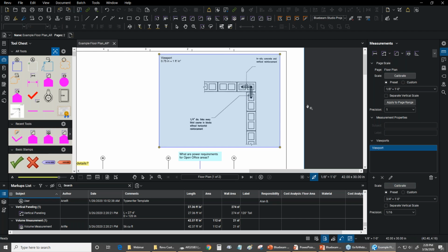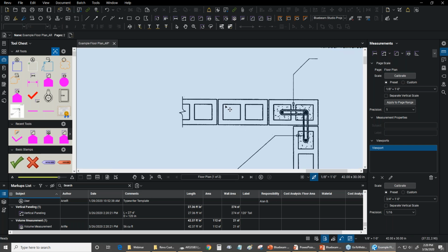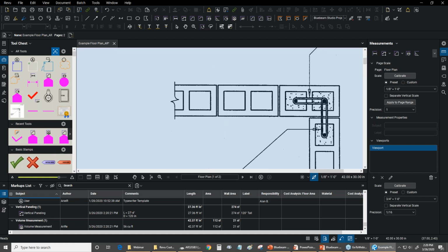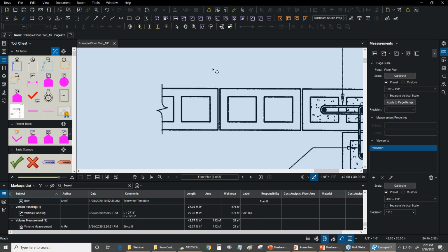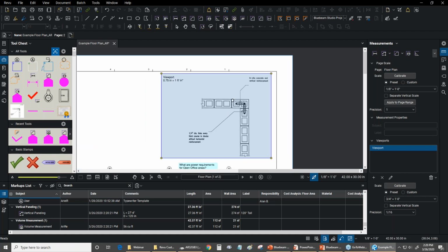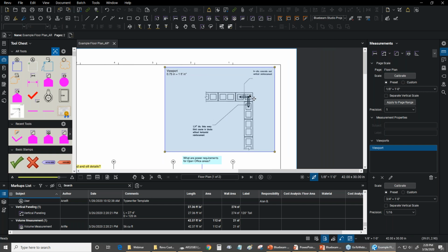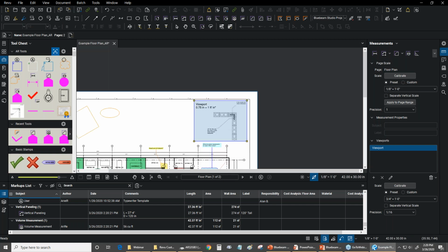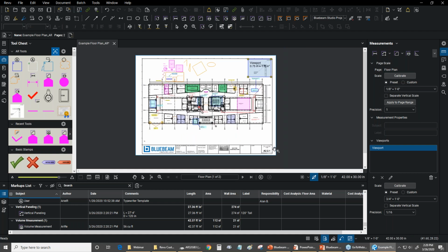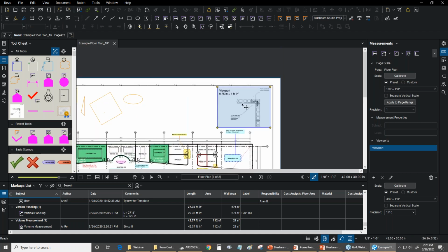This is the same place to go if you're trying to get rid of an untitled viewport that came with the CAD program. So many of our clients have told me, oh, I open up my drawing, I try to calibrate it, and it's not letting me, and I don't know why. And every time I click on the calibrate thing, this blue screen pops up. And so now if I zoom in, you might find this screen a bit familiar. This is the blue screen that you're going to see all around your drawing. That's why I zoomed in. And in this case, we have chosen our viewport and we've made it in a specific spot. But if it comes from CAD, you can imagine that the entire sheet will have a viewport except for my title block. So that can be a bit of a problem.